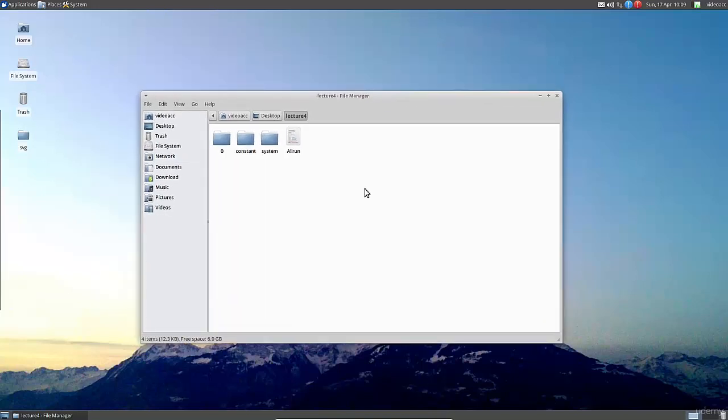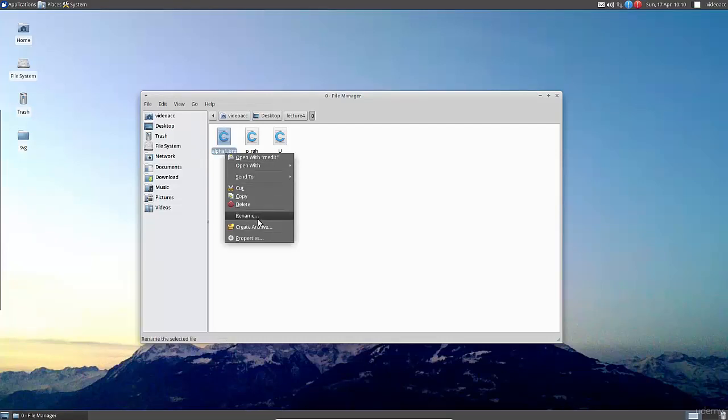Right, so let's clean up our folder. Delete the Allrun file, delete this alpha 1. We're going to simulate a laminar flow. So let's delete the k-epsilon files, the nut, nut tilde. So we just have our U, the static pressure, and alpha. Let's rename alpha to alpha.water.